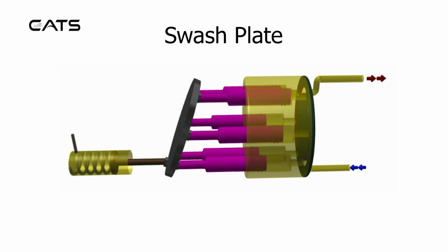The swash plate. This is an example of a variable volume, constant pressure pump. The whole thing is rotating. There's an inlet to which, in this case, there are 6 actuators, or jacks. As each jack moves, it draws in fluid, and as the swash plate turns, that fluid is expelled downstream. The greater the throw of the jack, the more fluid will be displaced.